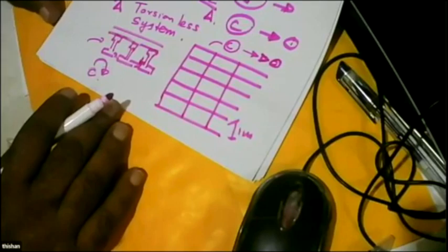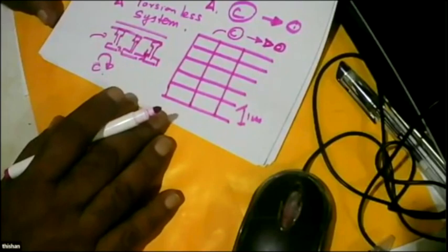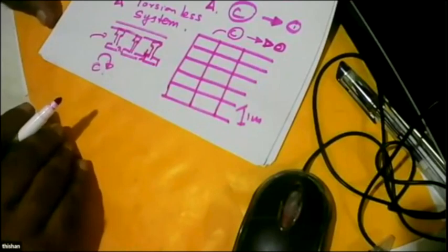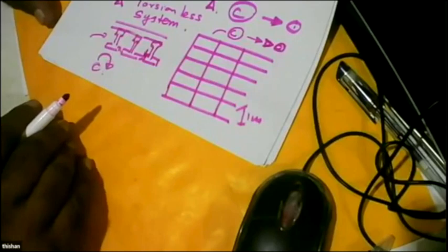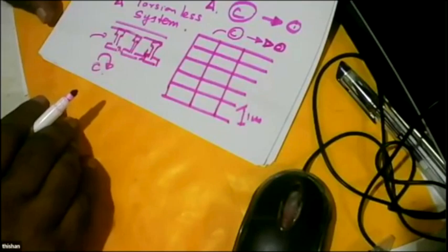The compatibility torsion situation comes when you have beams in 2 different directions, and you have a beam or slab situation, where the members are unable to carry torsion, but they can remain flexible while having adequate flexural strength. So that is one situation.